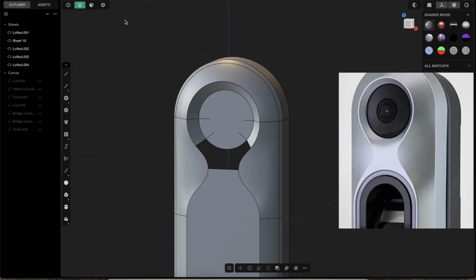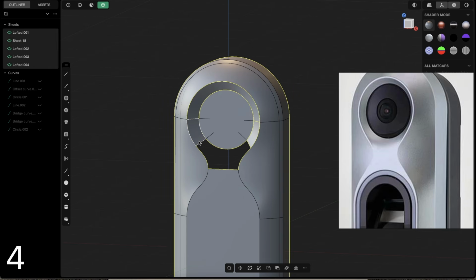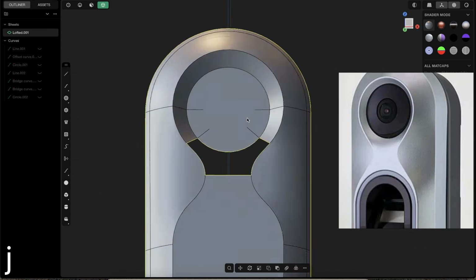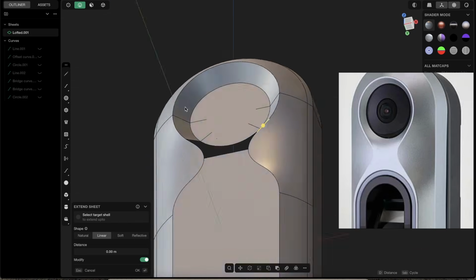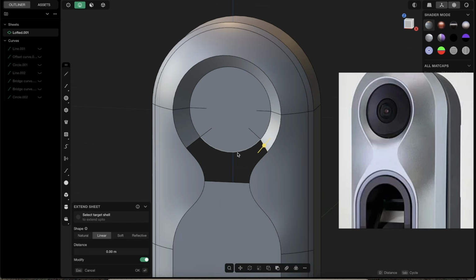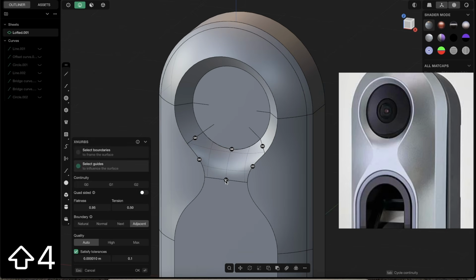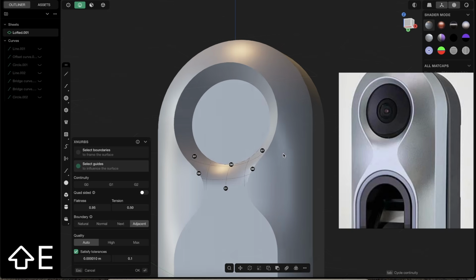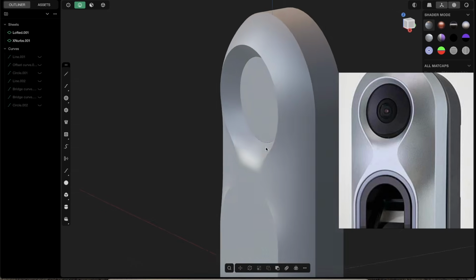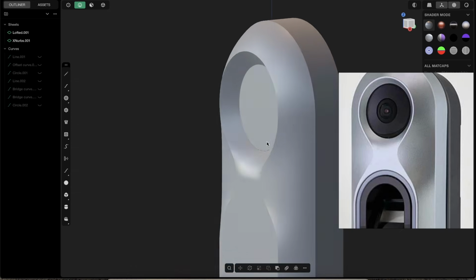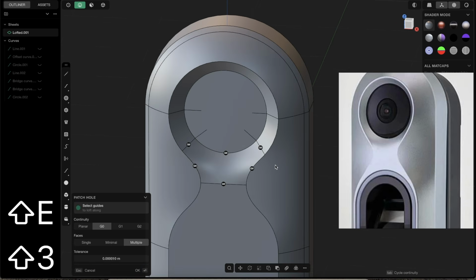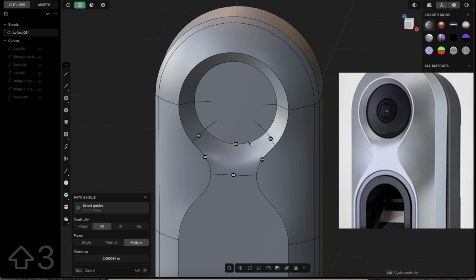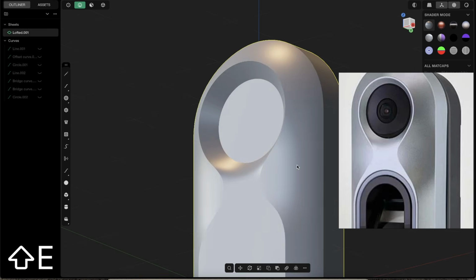Right click, and this looks perfect, because now if we press 4, we select all of those different sheets and join them to one piece. And now you are left with this nice shape, and this looks very doable for patch or xNURBS. So you can just alt click and, for example, xNURBS that and give it G1, G1, and G1. And if you right click, yeah, guys, look, it's just beautiful. But obviously you can also just use patch. So patch, and you see it looks exactly the same.